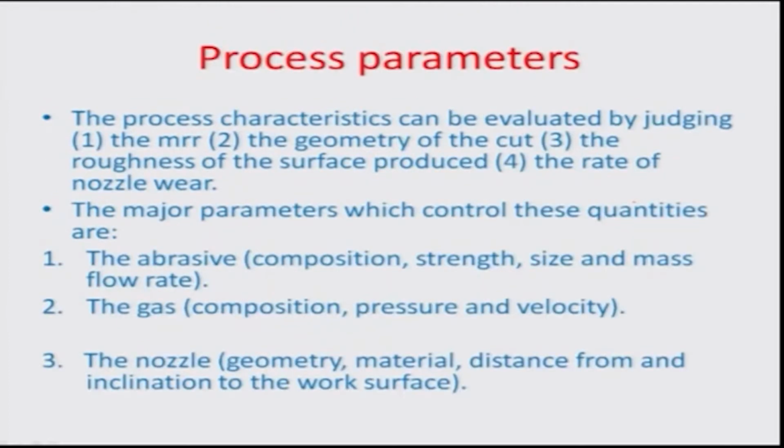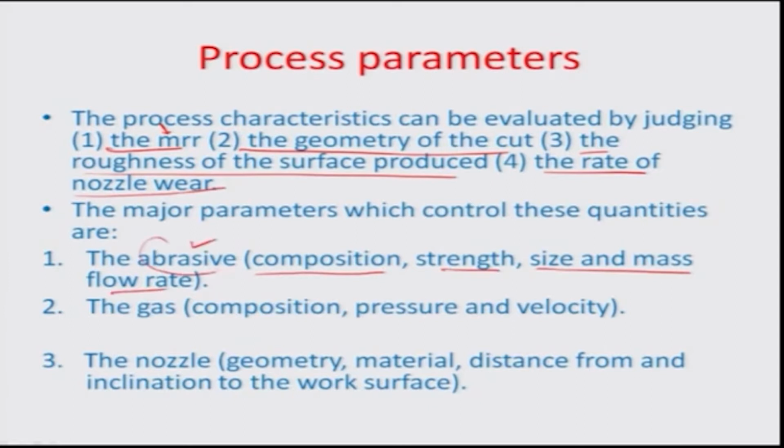So, the process parameters which are of importance here are obviously evaluated by judging the material removal rate, the geometry of the cut, or even the roughness of the surface that has been produced, and the rate of nozzle wear. And the major parameters which control these quantities are the composition, strength, size and mass flow rate of the abrasive, that is the main cause of the material removal, and also the composition, pressure and velocity of the gas which is responsible for flowing this abrasive at that high energy of impact or momentum delivery.